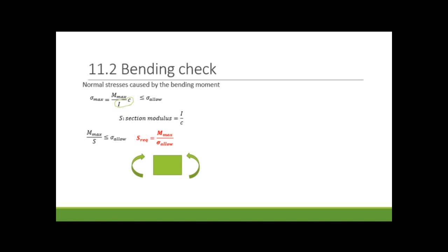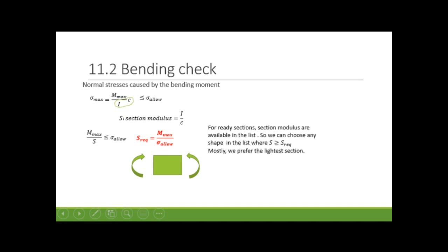We choose our sections related to this formulation. Therefore, our section modulus should be greater than the required section modulus.